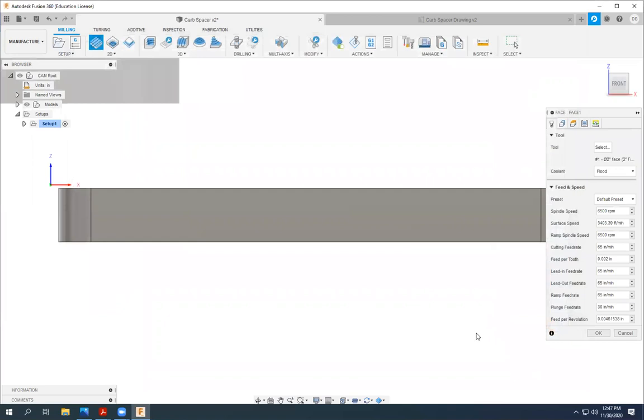And you can build tools in here too if you've got the patience or you need to model a certain tool. Fusion already has a lot of common tools modeled for us. We're going to disable the coolant. This coolant is usually not used on a face mill, usually used on other types of milling cutters.